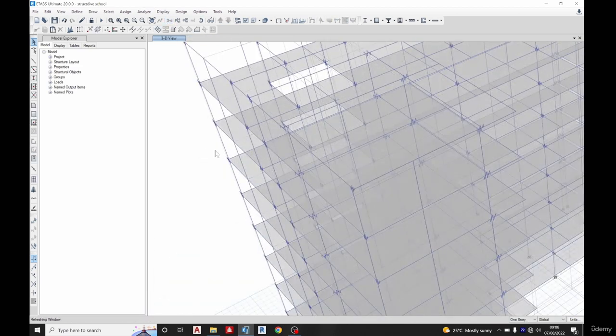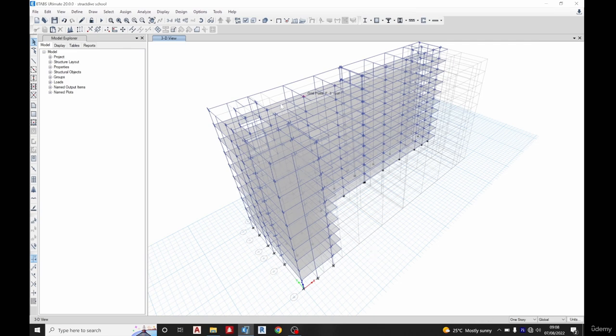So in this direction, we were safe because this place is wider than this. So all it did was reduce our maximum story drift in this side to 90 millimeters, and in this other direction to minus 56 millimeters, while in the positive y direction it gave us a value of 110 millimeters, and in the negative direction this side made it a value of minus 251 millimeters.